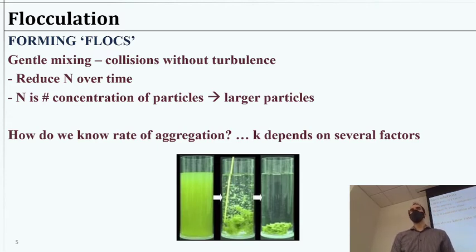For the flocculation chamber, we want something a lot slower. Now that the coagulant has been added and is well mixed, we want to give it time to act. In order to allow the particles to meet each other and collide, forming new particles, we want to give gentle mixing. Again, we'll typically use a CSTR. Of course, we could use a batch reactor for this as well, if we wanted to do just a batch at a time. But typically we'll use a CSTR, and it'll be gentle mixing, typically a larger chamber.